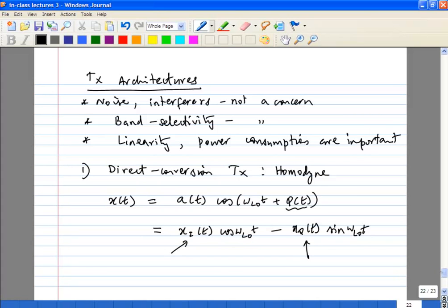Baseband will do both phase manipulation and amplitude. Yeah, baseband can handle everything. And will its output be a single signal, or two signals, Xi and Xq? Yeah, it will have two sets of signals, Xi and Xq. In fact, in general, the baseband will typically give you Xi and Xq, but each of them will be a differential signal. So you'll get Xi, Xi bar, Xq, Xq bar, so you'll get 4 lines.